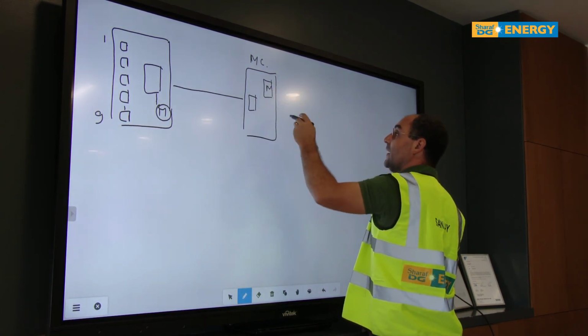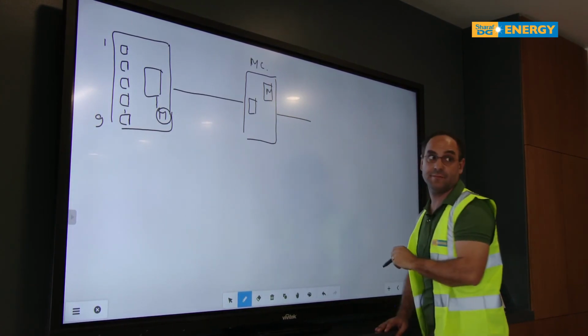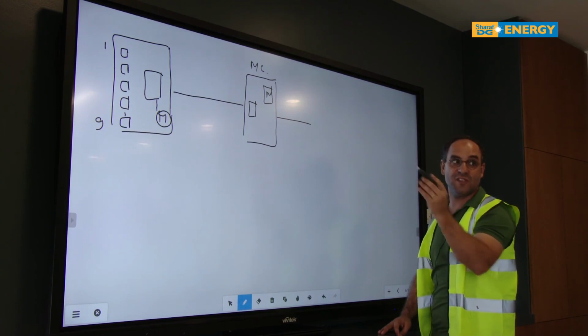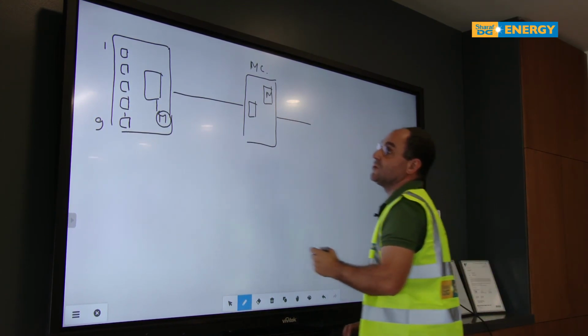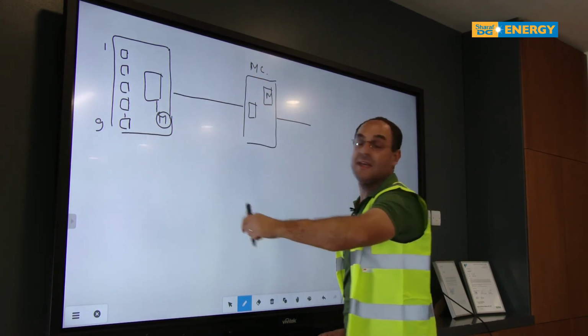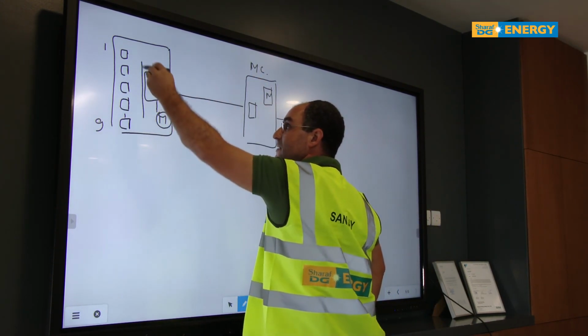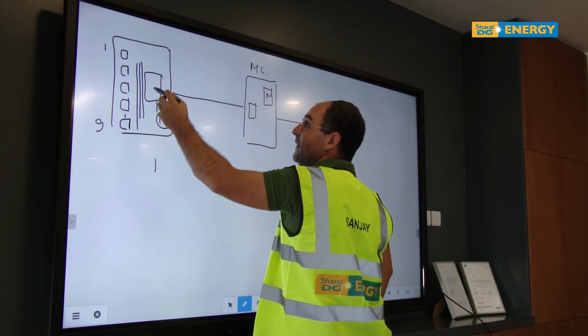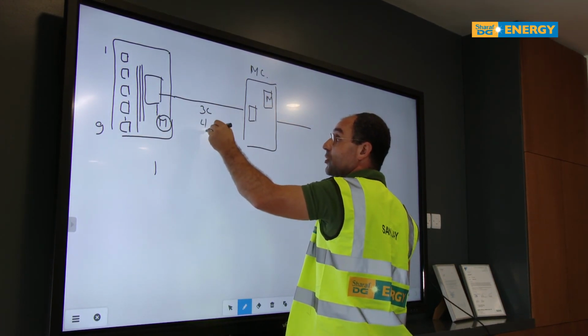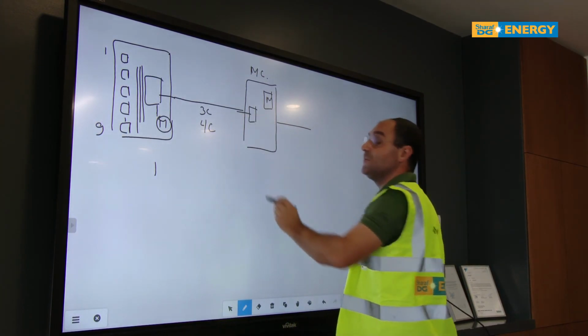And then we have the point of connection. We will see the details on your project. This is only schematic. So current generated by the DC side has been converted to AC and delivered here. There is the bus again, and then we take it from here. This is usually a 3-core or 4-core cable, and then you deliver into the meter cabinet.